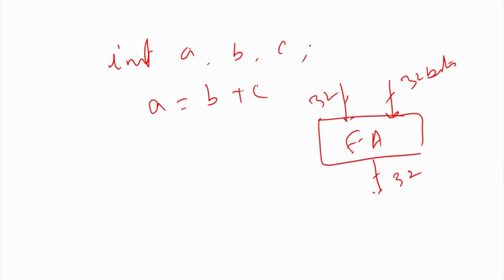So, the problem is that if the data values you are going to use are very small, you should not use integer, you should use a very customized integer type, which is 10 bits or 12 bits. And you might ask the question, how do I represent 10 bits or 12 bits in C, right?